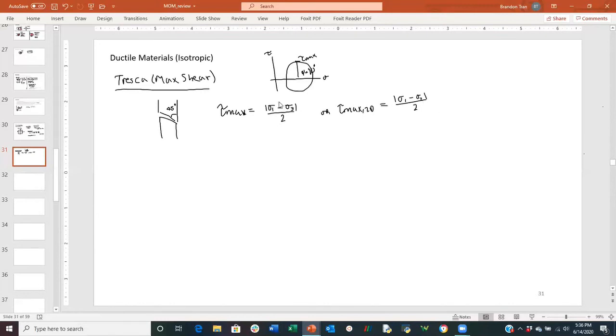So the failure criteria, so many people have different criteria for yield. They either consider the yield strength or the ultimate strength. We're going to use what typically people want to analyze. It's yield strength. They want the material to remain in the elastic region. They don't want it to plastically deform. So if the material plastically deforms, we assume it just fails. So we'll assume that the failure criteria is yield strength.